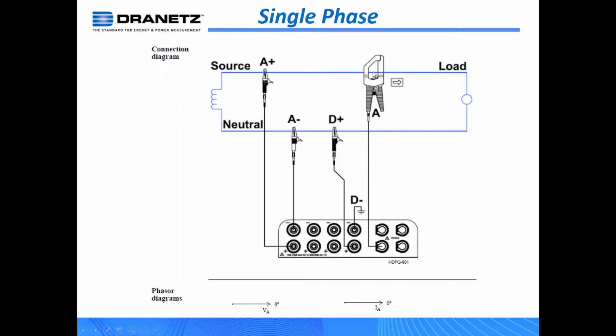Obviously, you want to monitor current. This scenario here, this diagram here is going to give me both power quality monitoring and energy monitoring. Obviously, because I have current and voltage, I have the energy component of it. Current is also very important as far as determining directivity or the source of the event. And so having the current information at the time you have the voltage event is a key component to determining, if we go back to a few slides earlier, the finger pointing. Do I point to the utility or do I point to the load? So that's very important there.